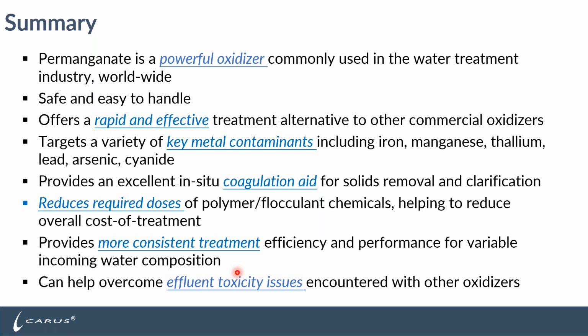It can provide an excellent in situ coagulation aid for solids removal and water clarification, and can potentially eliminate the need to add inorganic coagulant or reduce the required doses of polymer flocculant products. It can provide more consistent treatment efficiency and performance for variable wastewater types, and can also help overcome effluent toxicity issues encountered with other oxidizers, particularly bleach.